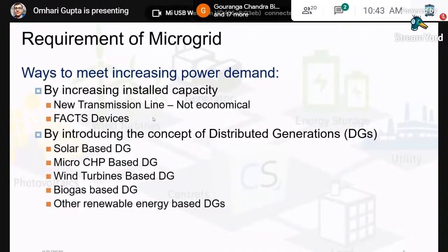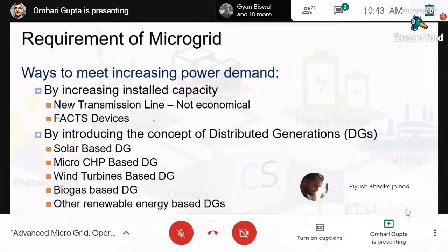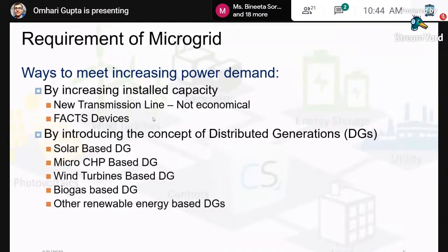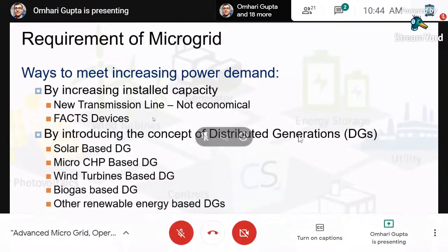That is to be taken care of. It is not that we can push any amount of power through any transmission line. There is one thermal limit always, and we have to keep the maximum transmitted power far below the thermal limit. Okay, so that is one aspect, that you build bulk power stations.